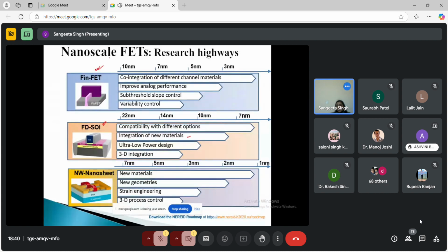We have all those semiconductor technologies which are based on FinFET. It is working fine for the 14 nanometer node. FDSOI is working fine for 22 nanometer. And if you are talking about FinFET, it is working fine for 14 nanometer. Various practical products are there based on 14 nanometer FinFET. It was very well there back in 2017 itself.